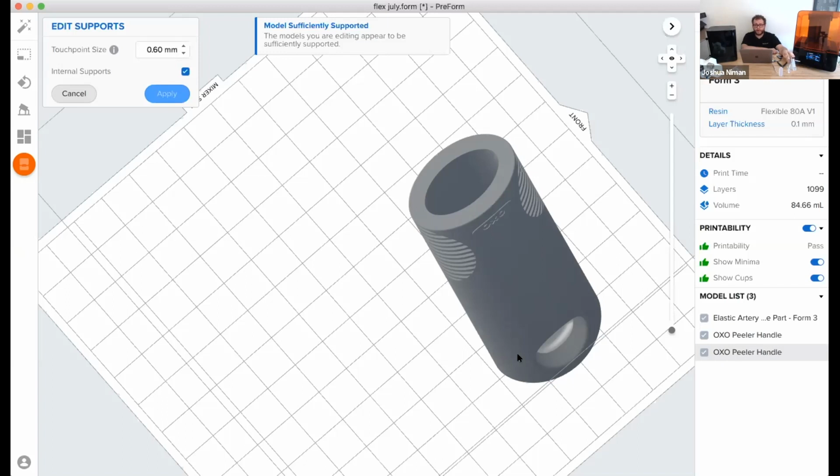Cool. We are still supporting the Form 2. Some people got nervous. We are not dropping all consumable support. We are not being super limited in terms of materials for the Form 2. If we can physically get the material to run on the Form 2, we're offering it. It might be a little bit different of an experience. You might need larger touch points to keep it anchored, but generally this material is such an improvement over Flex V2, to be totally honest with you. You are going to get a better result on your Form 2 than the older material, and I would say it's worth a shot. I think you could probably still try to use those 0.6 touch points.